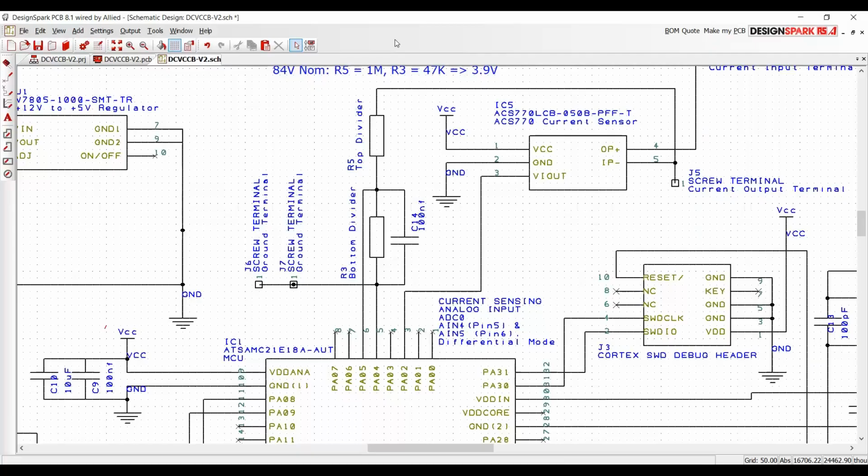Okay, now we're back over here in the schematic, and when I designed the board, I naively thought I can read the current sensor with an analog input pin, great, and referencing an IO ground. And then I can read my voltage input on 2 of the other pins and do a differential read between these 2.